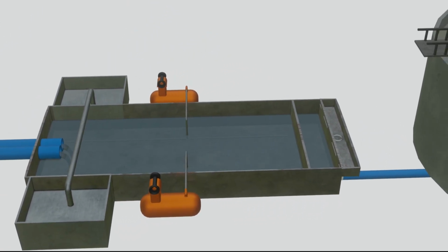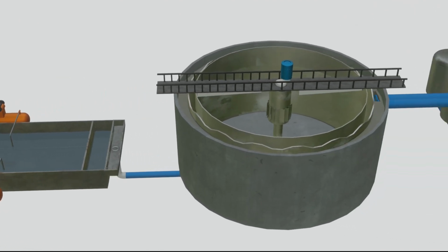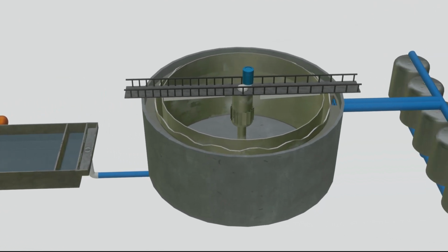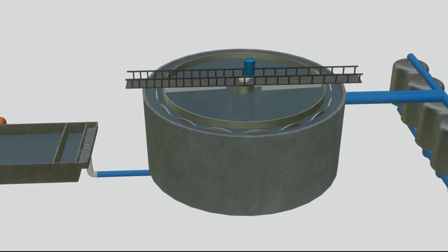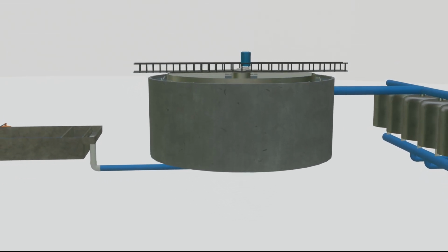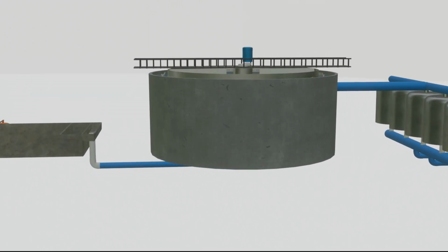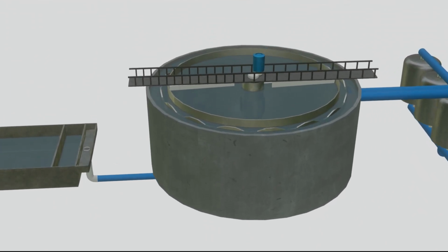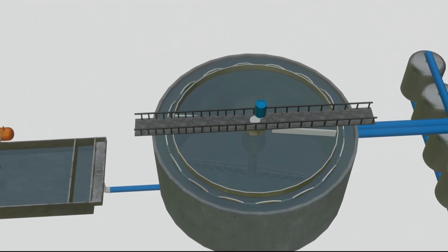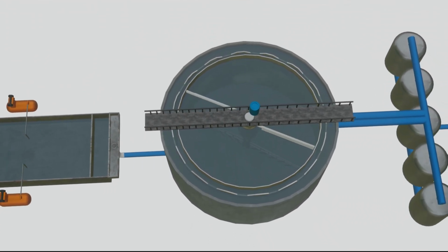After passing the aeration process, wastewater comes to the secondary clarifier. The microorganisms need time to eat all the bad stuff and decompose tiny particles that are still present in the wastewater after primary treatment. The secondary clarifier is a large tank, 3 to 5 meters in depth. Wastewater rich in microorganisms will settle in this tank for a period of time. The oxygen keeps blowing into this tank to keep the condition aerobic.